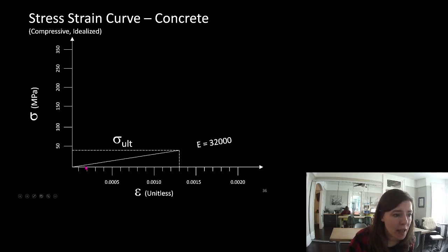And look at this. They applied load and checked the deformation, applied load, checked the deformation, and they did it up until this point, and then it broke. Anywhere along here, had they taken the load off, it would have reverted back to its original shape. There would have been no permanent deformation up until it failed, and that was its ultimate stress. The area under here was the energy that went into failing this object.